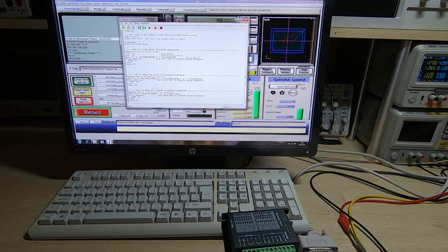And if we get to this point, it means we click the OK button, in which case it sets that same global variable to 1. That's just a flag to let the M6 end macro know that it can do its thing and continue. So we save that to the global variable here.